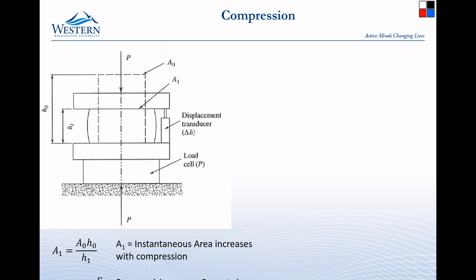So what happens is they will shear off at a 45-degree angle and the material will slide sideways. So it's a different failure mechanism. So there will be a shear strength of materials that you can look up, but for most materials, it's very hard to find a compressive strength. The place that you can find a compressive strength is for materials that are brittle. And so glass and ceramics, you can find a compressive strength. But anything that's squishy at all, you can't.